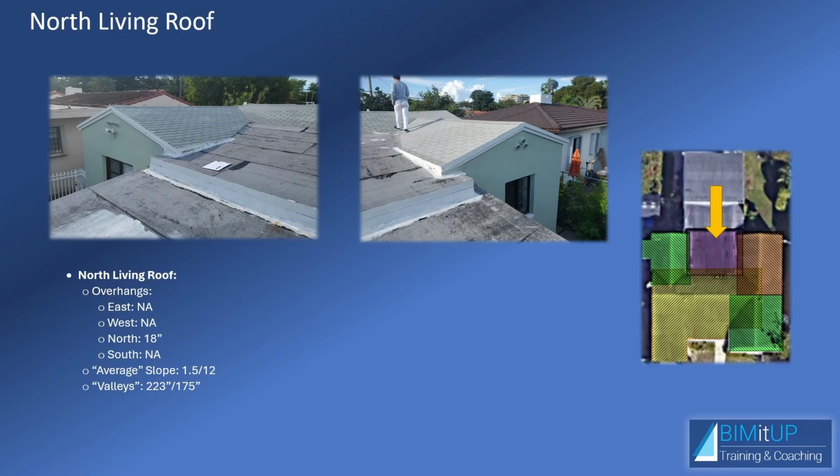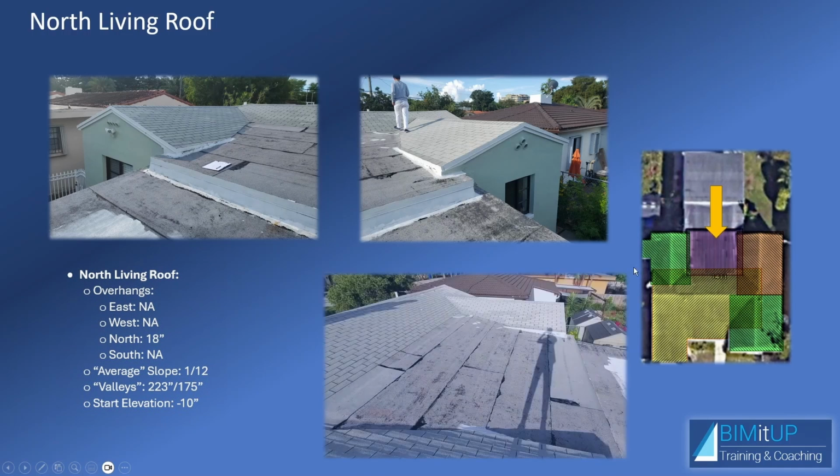As far as the characteristics, we have no overhangs to the east and west because of the situation I just described. Then to the north, you have an overhang of about 18 inches from the north wall. To the south, we have no overhang. It's going to be extending south to meet the main roof. The slope is 1 in 12, sloping up towards the south. And it has two valleys. This one here, which is about 175 inches, and then this one here, which is about 223 inches. Again, those are just approximate measures that I took on the roof just to make sure that we're on track.